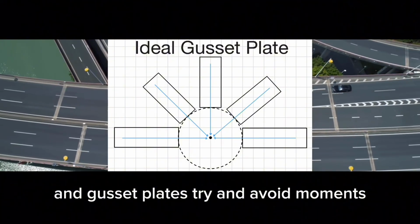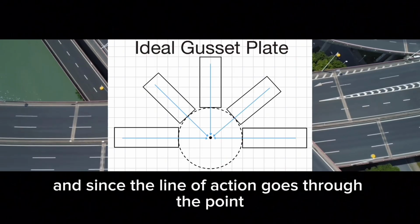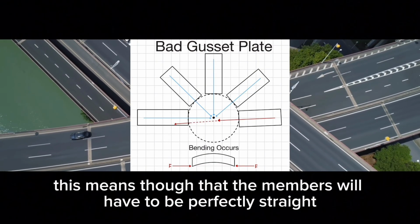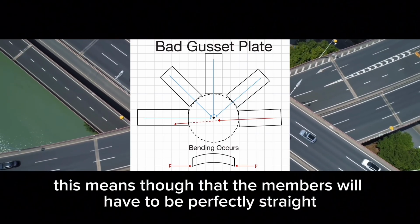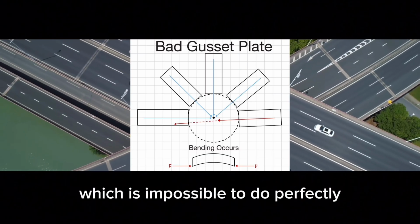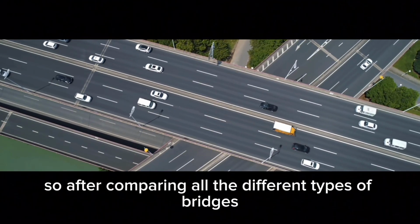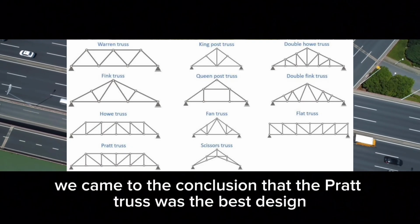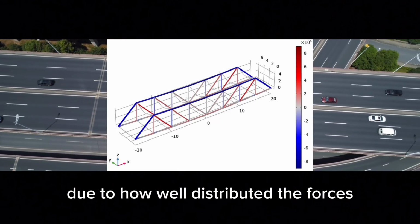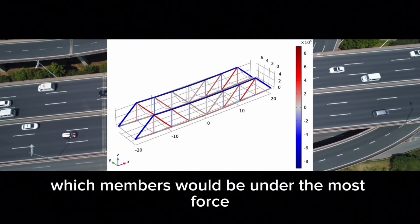Gusset plates try to avoid moments by having all the forces line up and intersect at one point. Since the line of action goes through the point, no moment is created. This means, though, that the members will have to be perfectly straight and in line with the joint. Otherwise, the force will cause a moment, which is impossible to avoid perfectly, which is why we have factors of safety. So after comparing all the different types of bridges, we came to the conclusion that the Pratt truss was the best design due to how well distributed the forces are and how easy it was to predict which members would be under the most force.